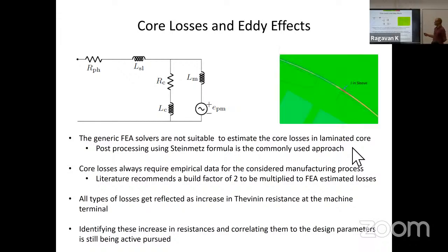So one such example: in some PMSM machines, they use a retaining sleeve to protect the magnets. In applications where these are mass manufactured, the sleeve used is normal mild steel. It's a conductive material, so because of the harmonic content, there are additional losses in the sleeve.